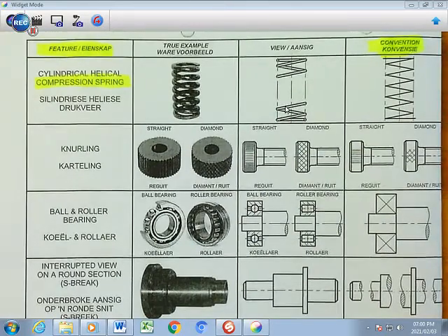Let's go to the knurling. The knurling with the silent K is this component here. It's a wheel or a handle that has almost like grip sections on the outside, and the grip sections could be either in a diamond format like it is there, or it can be just in a line format. That is to allow grip so that it doesn't slip when turning or closing grip components or handles. Right? That is what the knurling convention looks like. Straight lines, or it has a diamond shape as you have it there. Alright, that is basically what a knurling is.